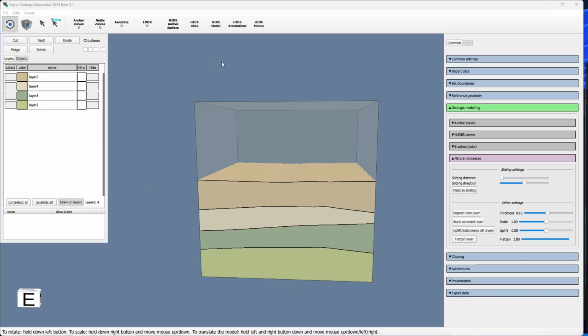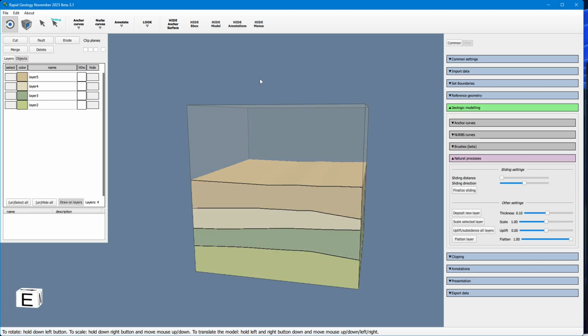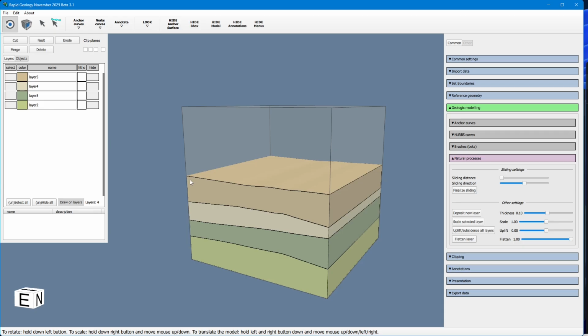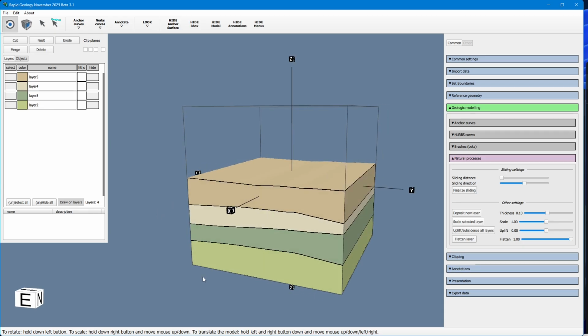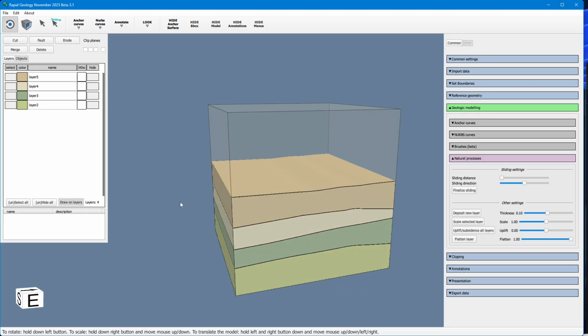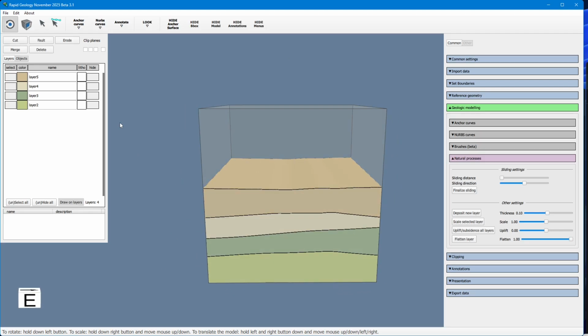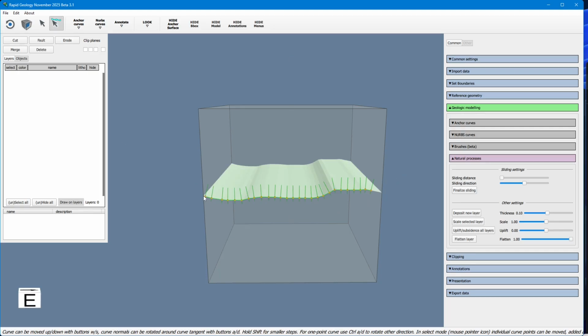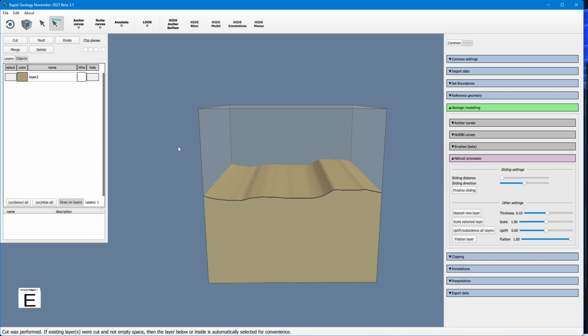The other way to use the faulting operation is when you want to recreate an illustration that has a fault. In that case, you don't want to perform sliding, you just want to draw it exactly as the illustration or the cross sections you have. How to do that is, let's just delete all of them. So one way to do that is that first you create the solid, then you fault it in the blocks.